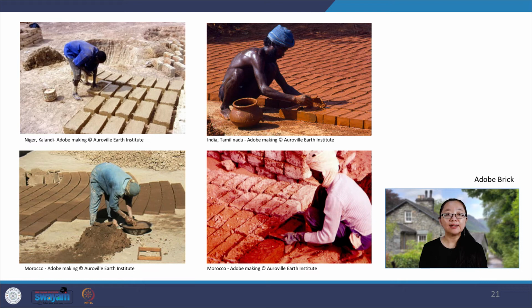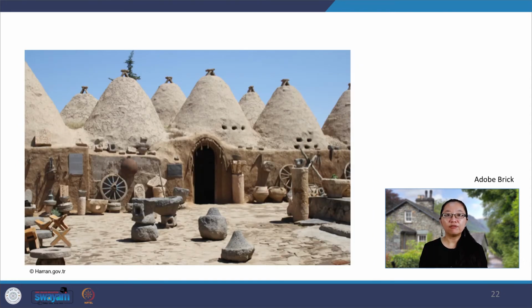Normal bricklaying techniques are used using earth or lime mortar. Earth bricks have load-bearing structural properties but provide poorer insulation compared to the dug-out, rammed earth or earth-sheltered spaces mentioned before. There is a huge variety of vernacular buildings worldwide using this Adobe brick form. One of the most notable ones are the beehive vernacular houses in Harran, Turkey, which dated back in 1750.